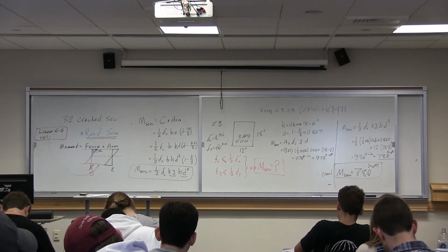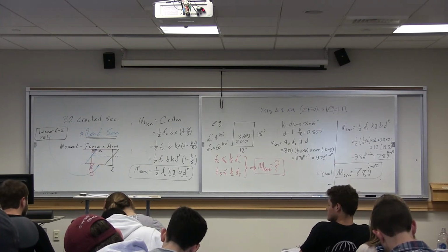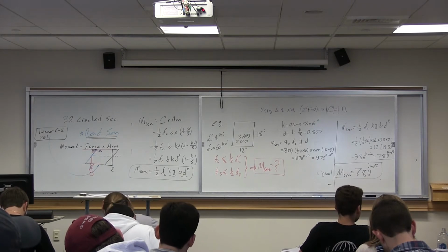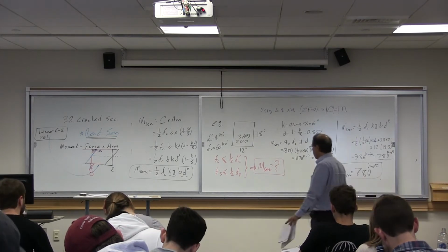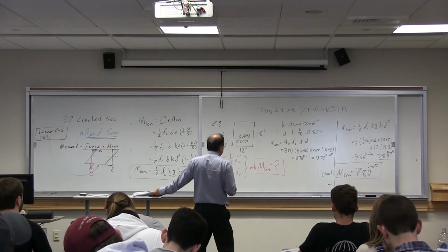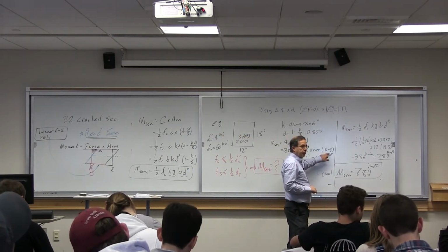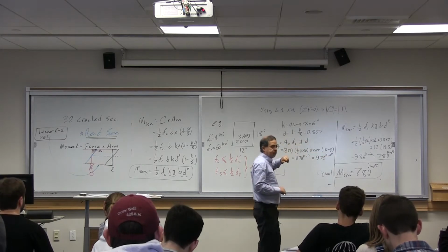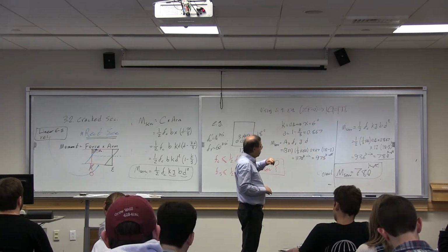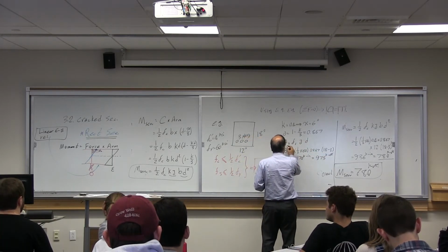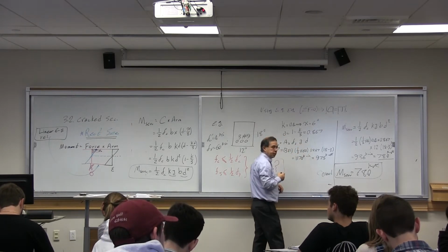Questions? For the arm length, for D, we go with 18 minus 3. This is not arm length, this is effective depth. Arm length was J times D. Just look at this equation. As Fs JD.